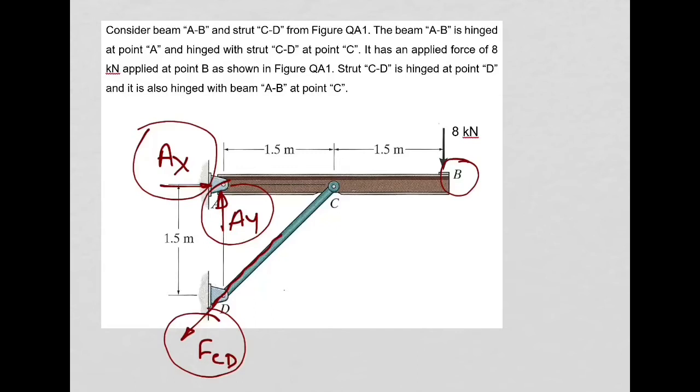If you added a hinge there, of course, you would then have to replace this hinge with these reactions, right? But then this is not a statically determinate structure. You cannot solve it with these methods we are doing, equilibrium equations. You need to use energy methods. It is a different story. But you don't have this hinge here.